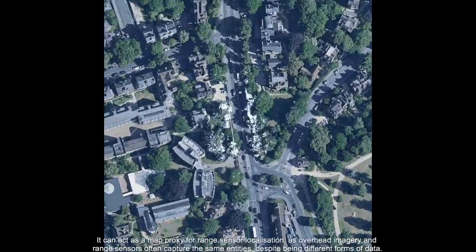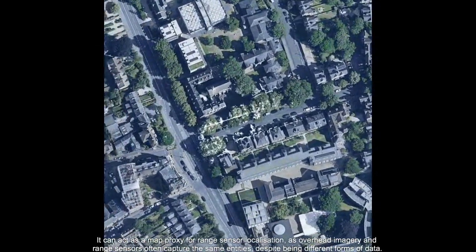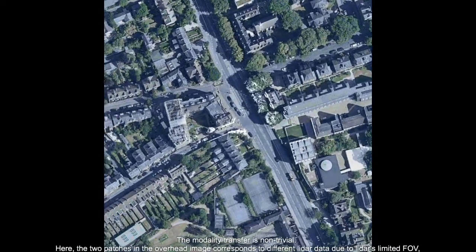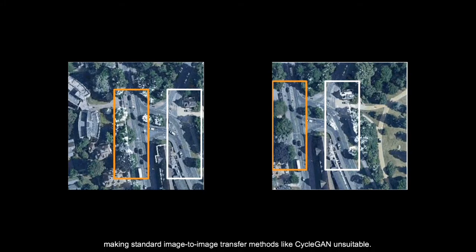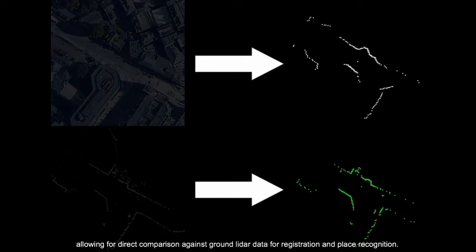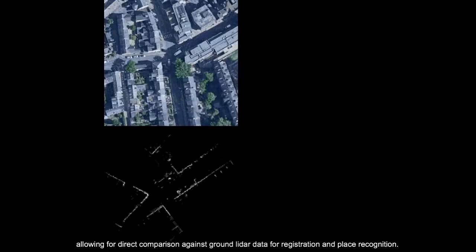It can act as a map proxy for range sensor localization, as overhead imagery and range sensors often capture the same entities despite being different forms of data. The modality transfer is non-trivial. Here, the two patches in the overhead image correspond to different LiDAR data due to LiDAR's limited field of view, making standard image-to-image transfer methods like CycleGAN unsuitable. Instead, we show how overhead imagery can be transformed into a collection of 2D points, allowing for direct comparison against ground LiDAR data for registration and place recognition.